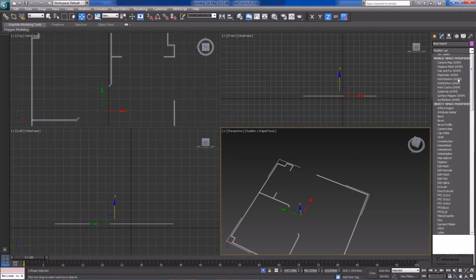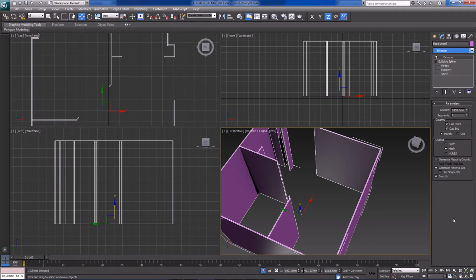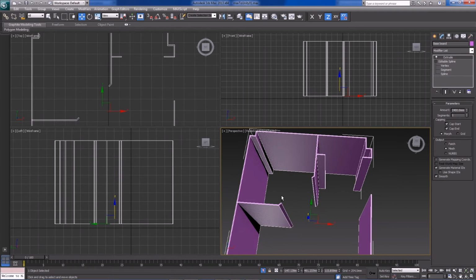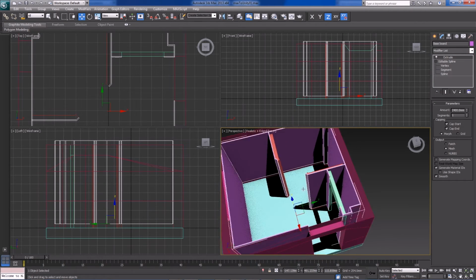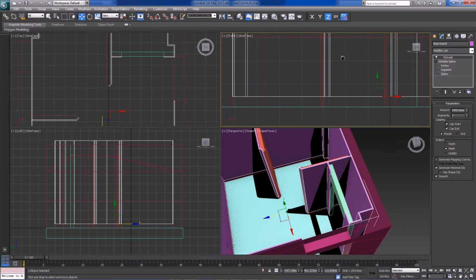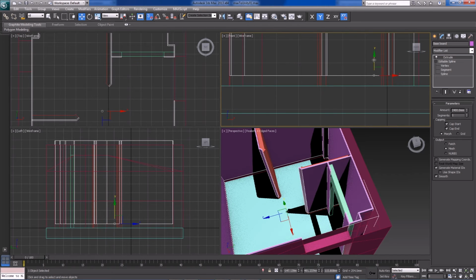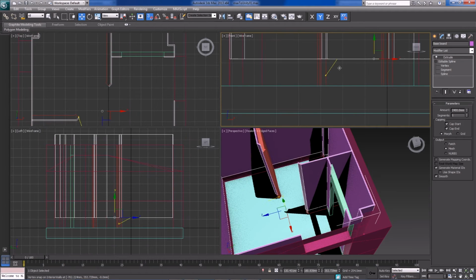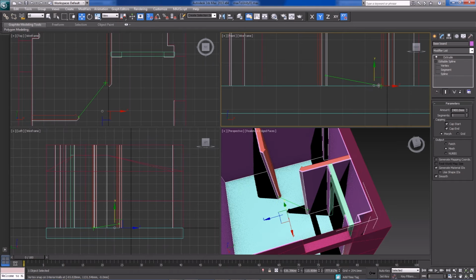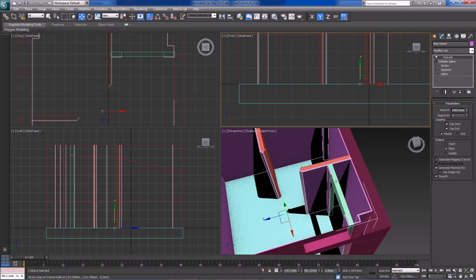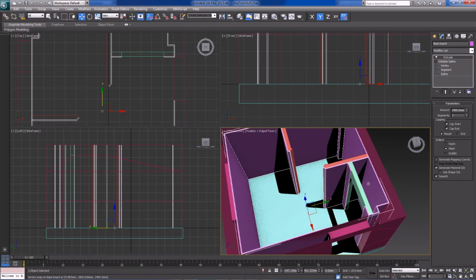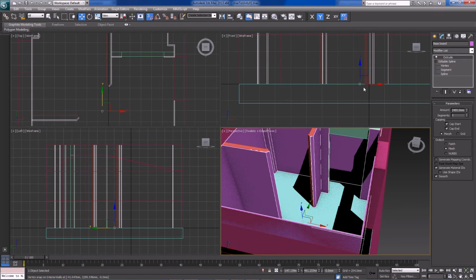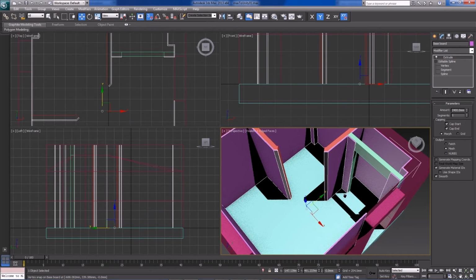Okay, so now we should be able to just extrude this. And we can, everything looks fine. That's absolutely lovely. Okay, so if we get out of isolation mode, we can see this is not at the base. So now I have clicked on Y, and because this is geometry, yeah, it doesn't snap. So there's something I've learned as well today, that geometry sticks to the axis when you try to snap it, but when you're in spline edit mode, it doesn't. You will go all over the axis.